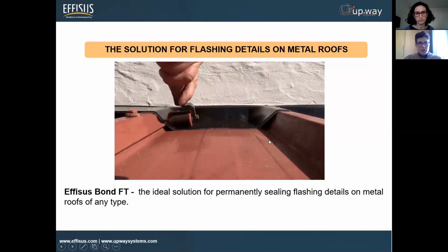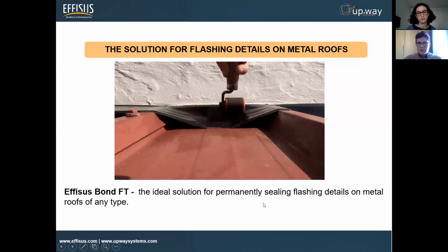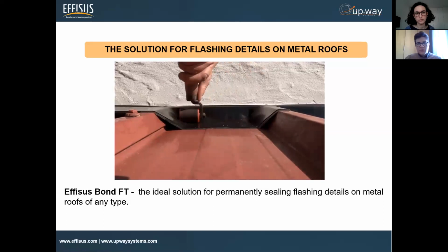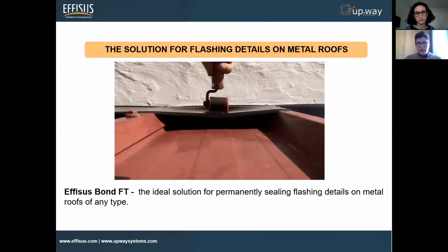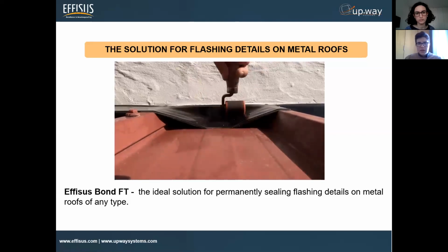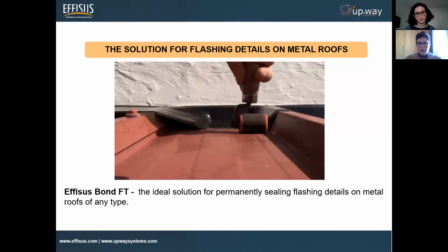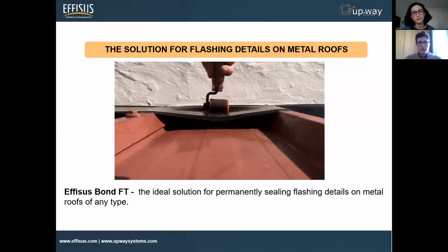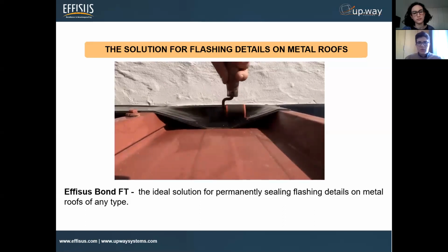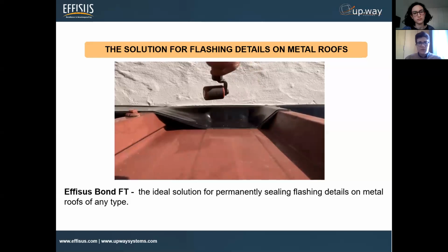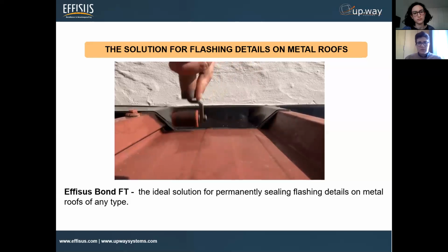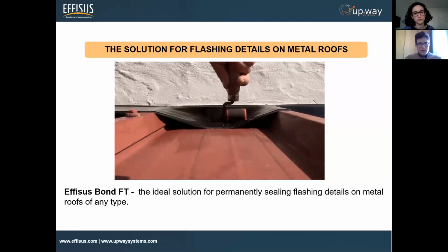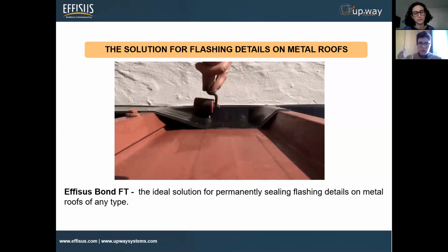What this membrane allows us is to completely seal all these types of interfaces, all these types of perforations, gaining the shape, gaining the form of the perforation itself. The composition of it is EPDM. We all know EPDM. It's been in the market for over 50 years. We have records since World War II, for instance, of how reliable it is. EPDM is 100% waterproof, and very UV stable in some cases when it needs to be totally exposed. So this is something quite different, and it is self-adhesive and uncured, as I mentioned.